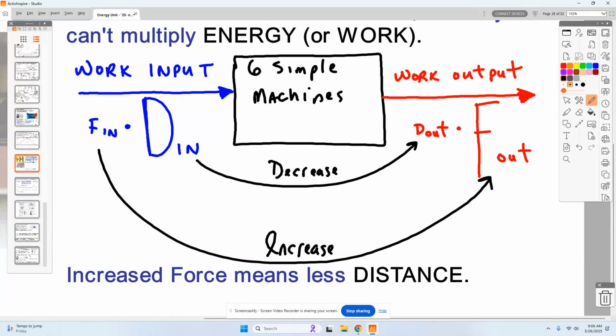The advantage of that machine was simply to change a downward force to an upward force. Now what we're going to do is create something called mechanical advantage. I'm going to move this closer to that. Now you notice something. When Seppi pushes down on this, go ahead and push down on that. You notice, first it was easier, wasn't it? You notice how far this thing moved down compared to how little this thing moved up. Do that again for me. Look how little that moved up compared to how far that went down. That's what we call mechanical advantage.